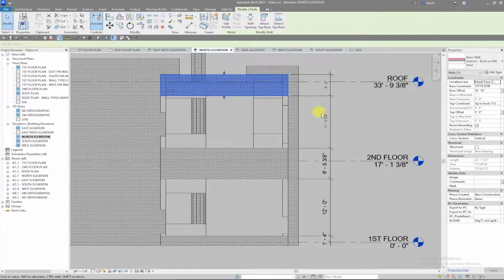This here is going to be 2'8" plus 10, so that's 12'8" above the second floor. So we can say, oops, the bottom is from the second floor and it's 12'8". Doing some quick math there, that gives us 10 feet there. And then this is just going to be the remaining 5'6" 5/8 that is shown on our final deliverable.